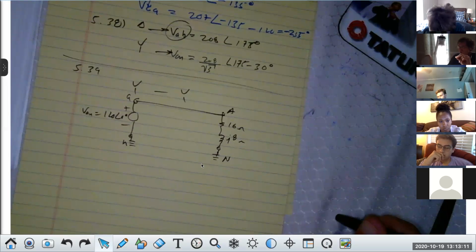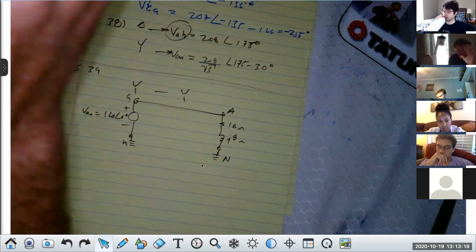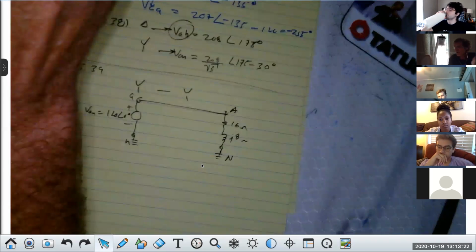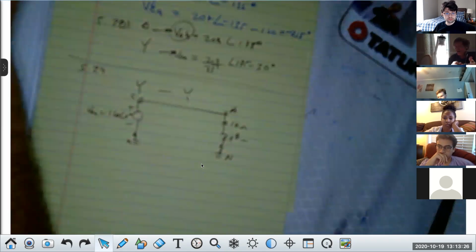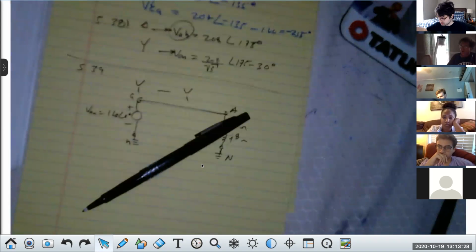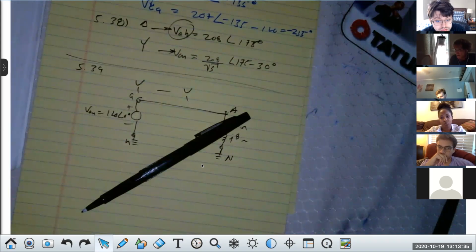How many have heard of the term earth ground? Any kind of wiring on a house ultimately has to have an earth ground somewhere that makes it a very low impedance path for any currents to go to ground. And that earth ground, the earth below you, technically is the return path to the power company if any other grounds break. Do you follow me?